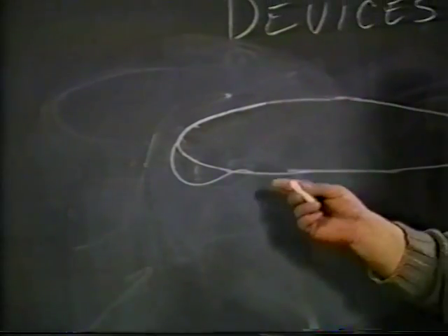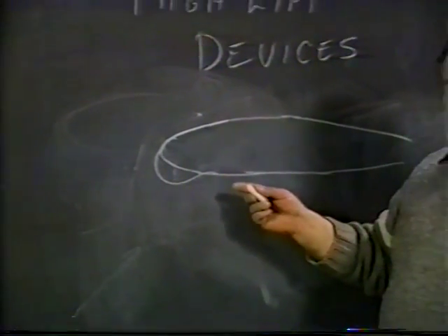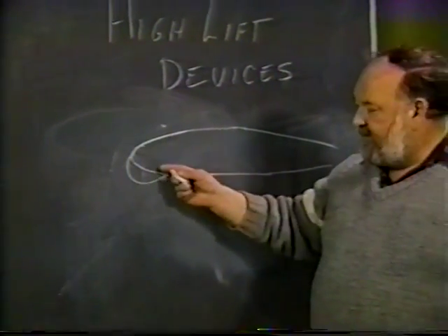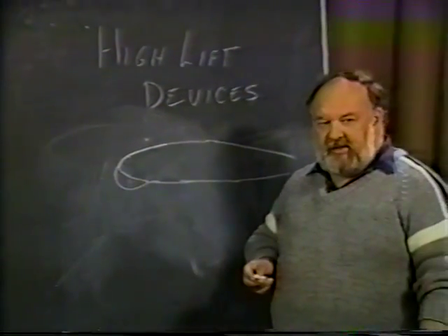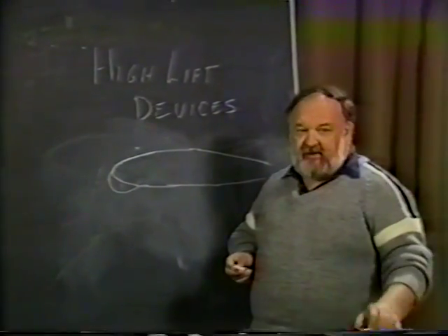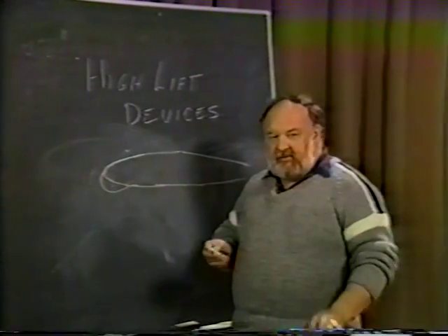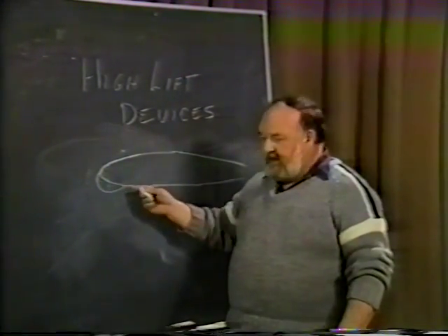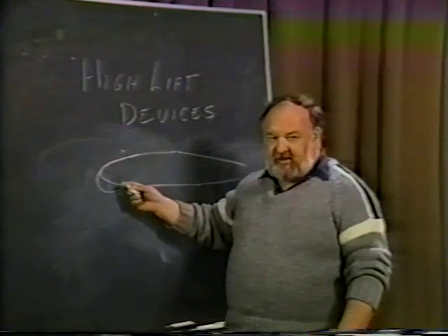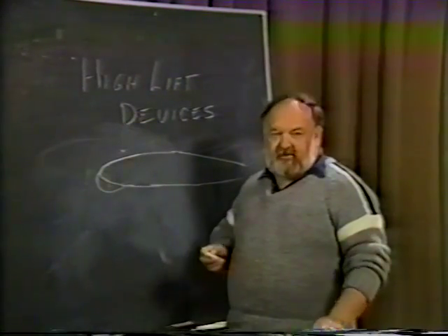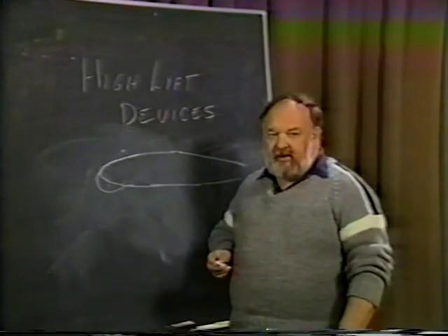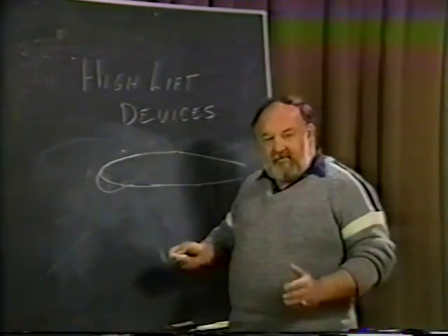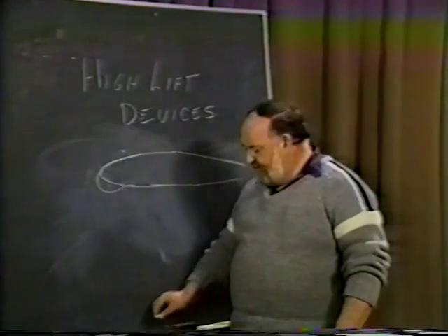Now, there are some aircraft designs whereby you want to take a standard airfoil and put a bulging leading edge to it like this and leave it there as a fixed entity, in certain portions of the wing to delay the stall of that particular section of the wing. But if you leave it, of course, you've changed the profile of that airfoil, and in most cases have increased the drag. But in some cases, the compromise is well worth it.